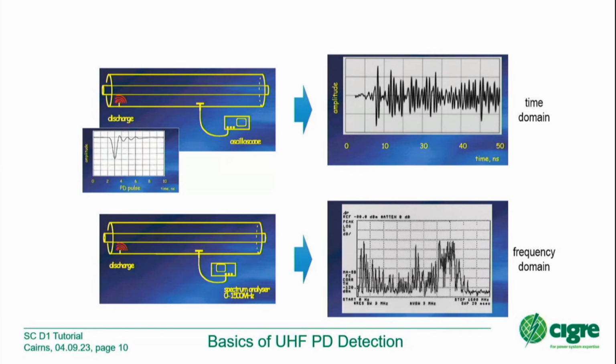Here for this example, we have a frequency spectrum from 0 to 1.5 gigahertz, and we saw a lot of spectral lines in the range from, let's say, 0 to 1.2 gigahertz. And the noise level will be a straight line, maybe here in this way. Sometimes we have 1 or 2 spikes from a radar, 1.1 gigahertz, for example. But this broadband signal in the frequency domain was generated by the partial discharge at that protrusion. So, that's all for the basics of ultra-high frequency PD detection.